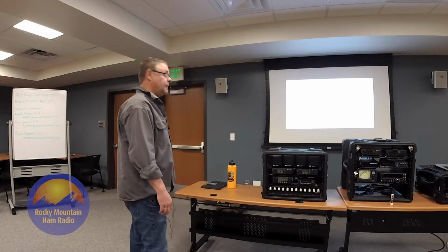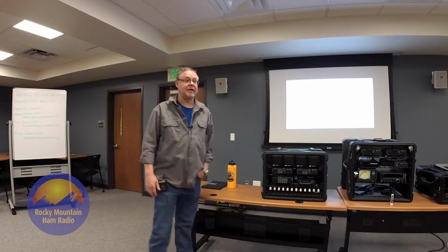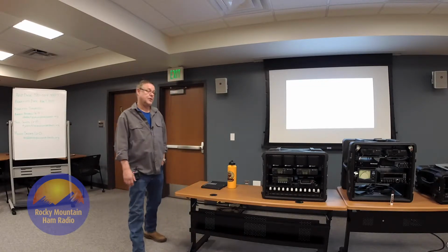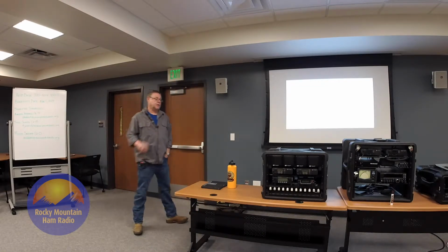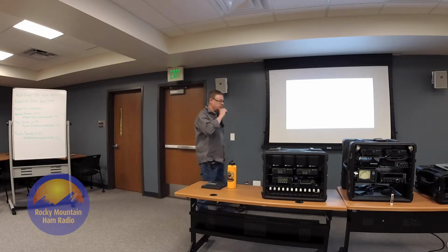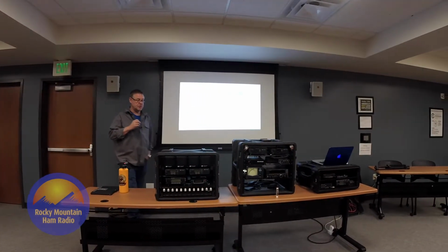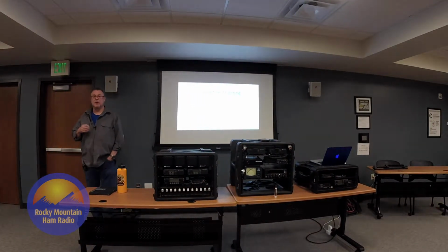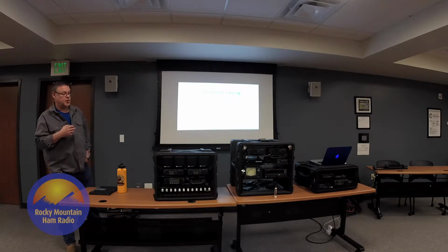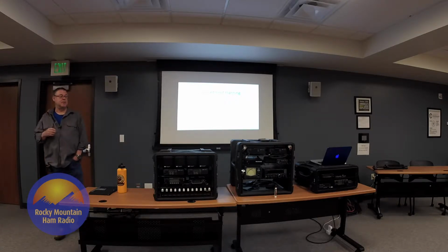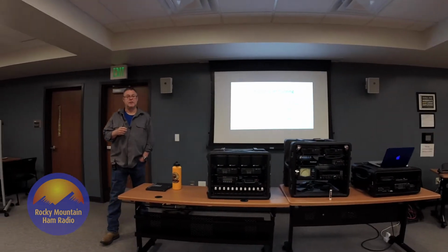Switching power supplies are a good thing and a bad thing. We're going to touch on that in a few minutes. Power supplies. The switching power supplies out on the market nowadays are very flexible. They're small. They take up a small footprint. They take up very little weight in your design. However, research them. Some of them are extremely RF noisy.